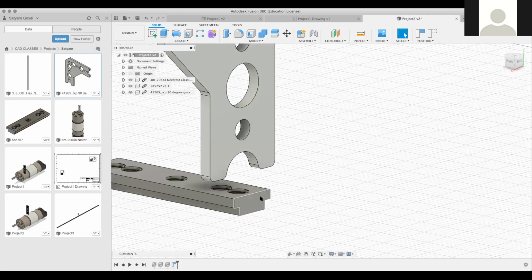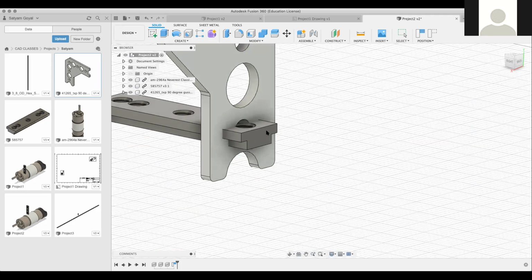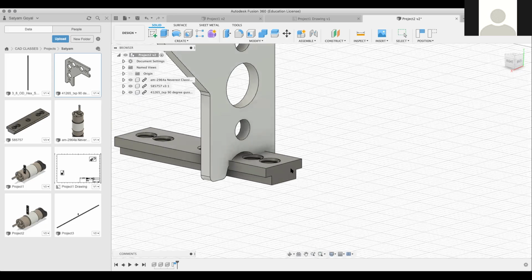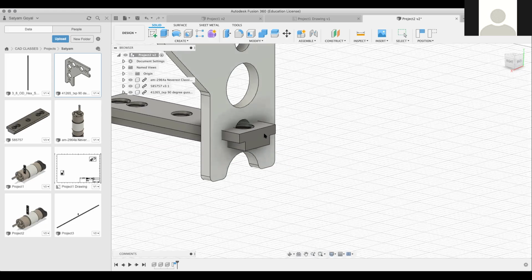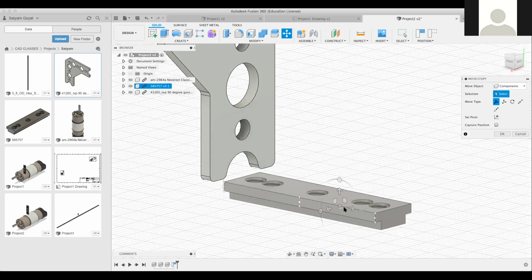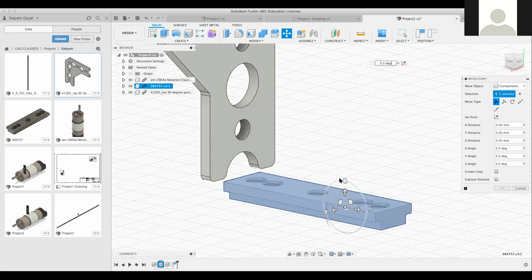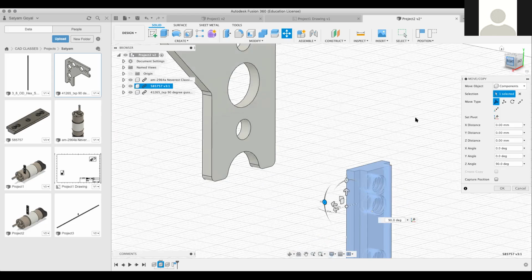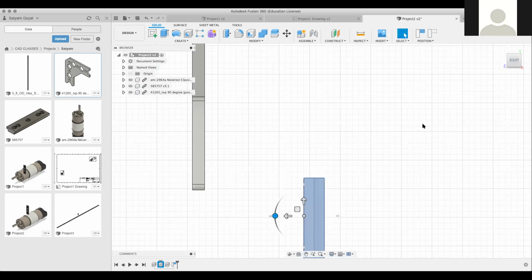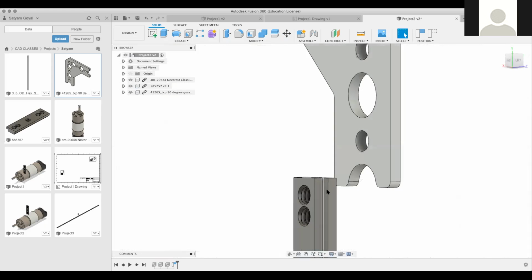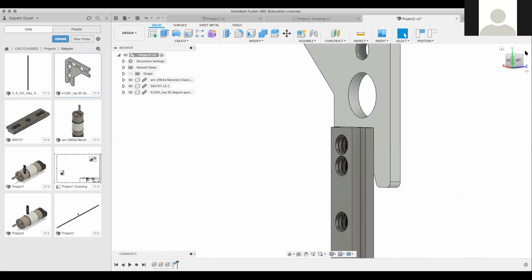But what he's saying is, I think he joined the two objects, and they ended up meshing like this. That's how mine went. It just meshed. Sometimes it meshes like this. So what you have to do in that case is undo the joint and, just like you said, rotate it in that direction. Now if you rotate it in this direction, it'll joint properly. It tries jointing it with the shortest possible moves, so that's why it might have jointed it like that.